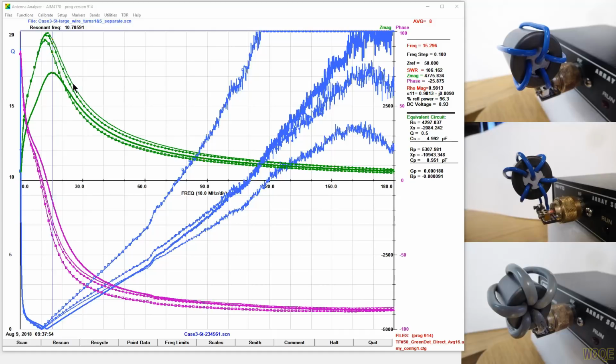And the green curve that has the highest impedance here is the one where the starting turn and the stopping turn were definitely apart from each other. Two of the middle turns were connected here, and the other 2 turns were in here. The worst case one right here was where the starting and stopping turns were adjacent to each other. The effect shows here that it's not terribly important whether the placement is done well or done poorly. So in my opinion here, it's not worth trying to say the starting and stopping turns are far apart. Now, when I wind these things, I usually make an attempt to keep them separate just because it seems like a good idea. But the tests show that it really doesn't make much of a difference.